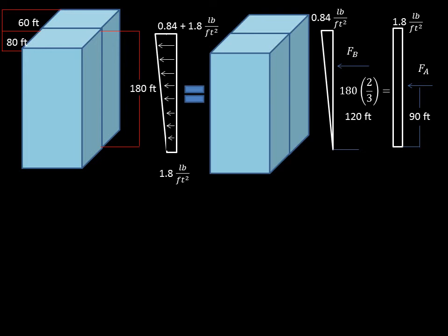Next, we evaluate the rectangular part. In this shape, we always locate the single force in the middle of the area of application of the distributed load. Now, we already know where it is located. Let us then compute the amount of force in those forces.